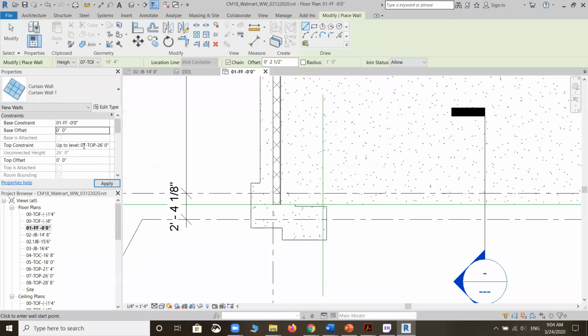But instead, you need to go to a top level. In our case, we really don't have a top level that is 9 foot 8 inches. Instead, we either have 0, 0 or 14 feet 8 inches. So this is up to you. If you wanted to use 0, 0, in order to avoid 0 heights, because you're starting at a 0, you cannot end at a 0.